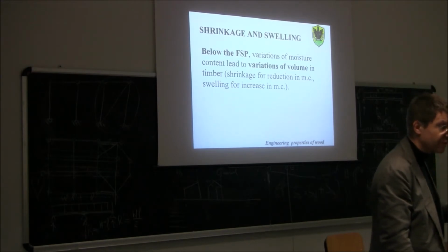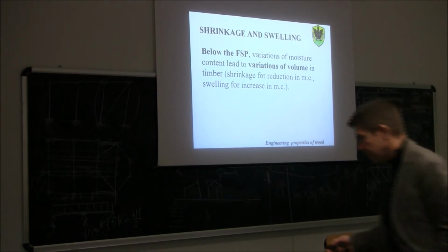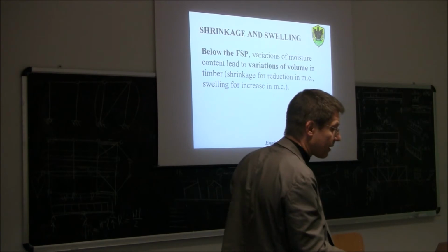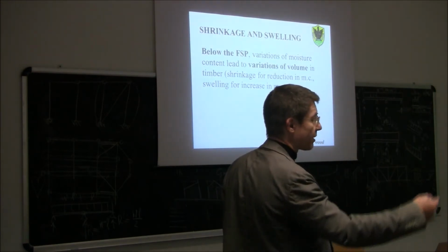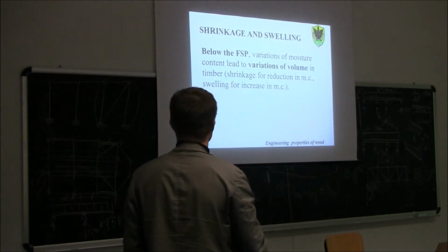You remember that wood is very weak in tension perpendicular to the grain, so only small values of stress perpendicular to the grain, for example those due to the shrinkage, may lead to structural failure, to the formation of a crack within the wood. So basically we want to dry in order to avoid the occurrence of cracking, the other problem, when the structure is constructed. We want to have this done before the construction.